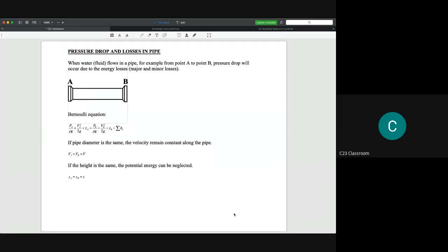However, in another application, sometimes we have a network of pipes, meaning a pipe connected with other pipes, and it creates a network. In a network, we are capable of calculating the flow rate by using the Bernoulli equation, but we will have a lot of unknowns. For example, sometimes we will have 6 unknowns, meaning you need to develop 6 Bernoulli equations from 6 different points. Then you need to solve them simultaneously, one by one, so it takes a long time. To simplify this, I would like to introduce you to the Hardy-Cross method. That is what we will learn in chapter 2.